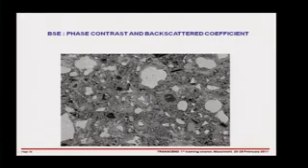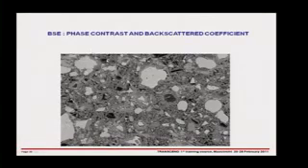To eliminate any parasite effects of surface topography, of secondary electron imaging, you have to polish your samples. You polish your samples to get something that's as near to flat as possible. And when you have a polished section, then you can really see extremely nicely and in great detail all your different phases. And what's more important, you can then analyze those.